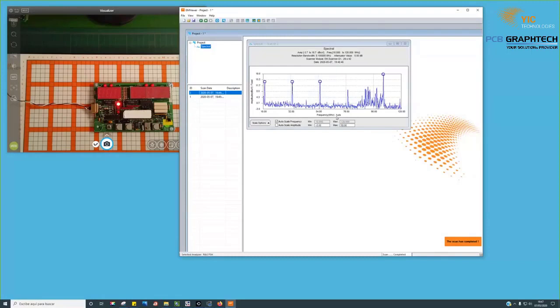This is the scale for the device on, minus 3 to 19. So I go to the other measurement and specify the same scale, minus 3 to 19. In this way, it's very easy to compare the difference between one and the other. I can create a specific node called the spectral comparison.